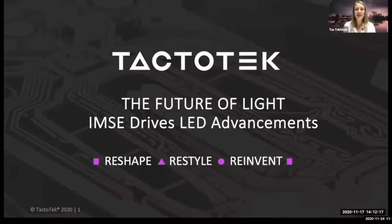In IMSE, it is not possible to use just any component available, but we have to select components that come in packages that survive the IMSE manufacturing process and especially injection molding, without compromises in the component interfaces or performance as a whole. Therefore, we work together in close collaboration with our partners Osram and Melexis in finding and developing IMSE suitable LEDs and controlling mechanisms for them.